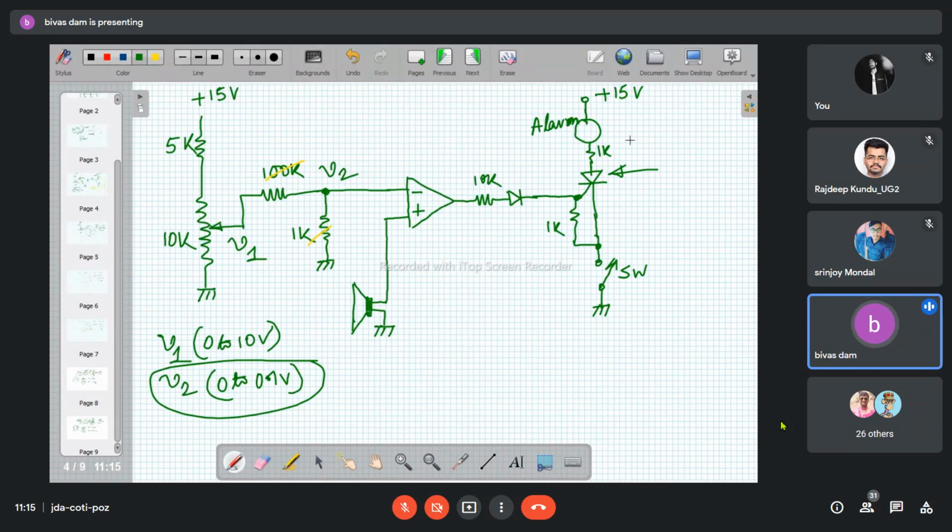Using a meter, say voltmeter or multimeter or oscilloscope, whatever it is, you go on monitoring this V0 output. The output of the comparator or the op-amp is V0. So what are the possible voltage levels of V0? Plus or minus V sat. Now, in case V0 is minus V sat, can there be any gate pulse? No, sir.